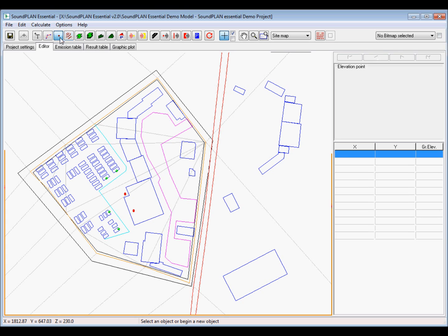The program will triangulate all the elevation data, including spot elevation and line elevation, to develop a digital ground model. The digital ground model develops the smallest triangles between the elevation information it finds. And with that, as we digitize from that DGM, the program already knows exactly the base height or the terrain height at that point.